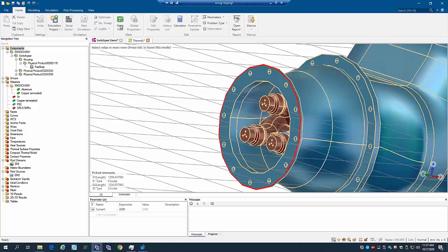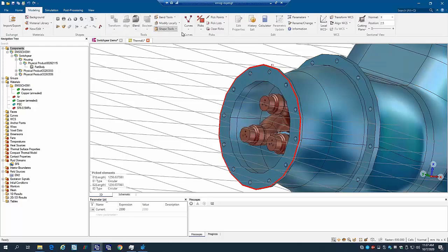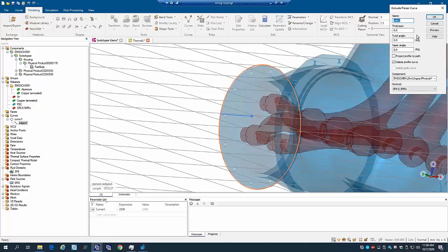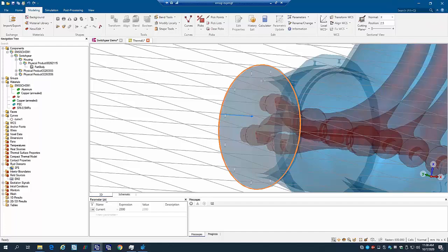Like here, I can go to modeling and change this selected edge to be a curve. And then I can say I want to construct a surface. Oh, actually, I want to do this, extrude the curve. The curve is selected. The direction, I learned last night, needs to be a negative number so that it's pointing to the other side. I said, okay, so this will be closed.